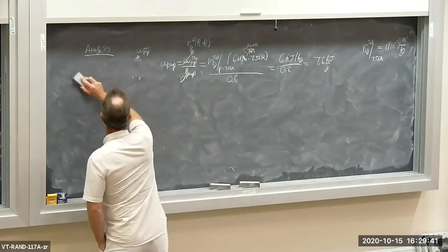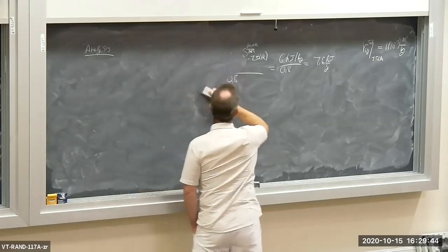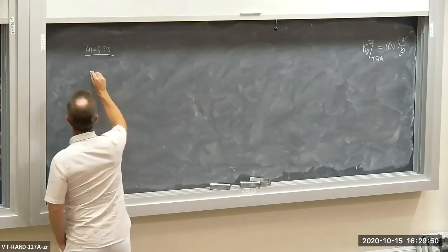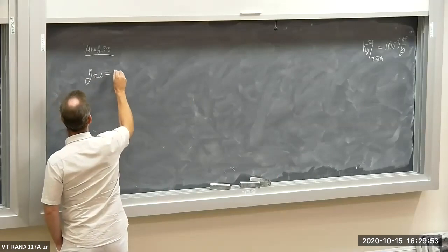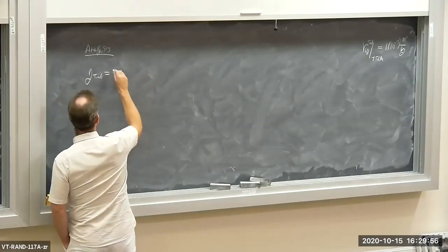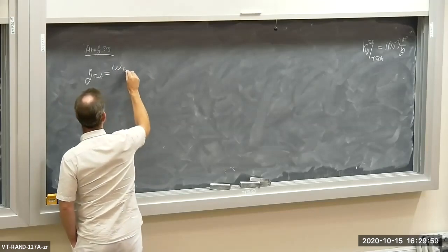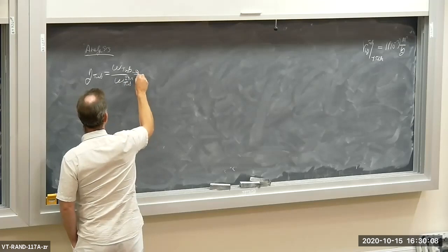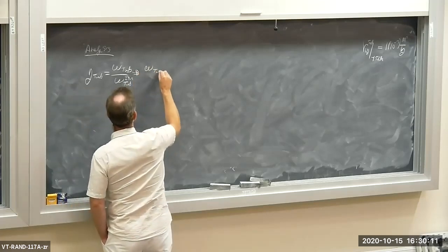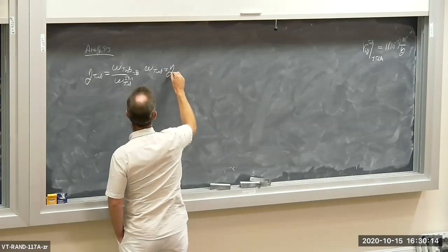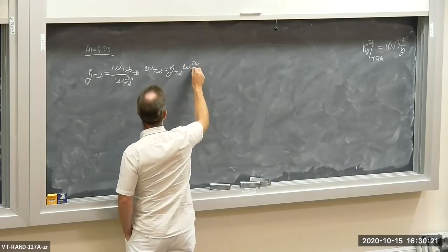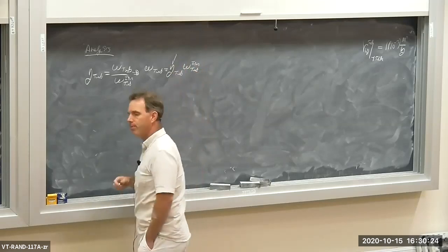So that's going to take a little bit more effort here. Let's use the isentropic efficiency for the turbine. The isentropic efficiency for the turbine is, mass flows are the same for the isentropic and the non-isentropic, so that's the specific work for the real turbine divided by the specific work for the isentropic turbine. So W turbine is equal to the isentropic efficiency for the turbine times the isentropic turbine work. Okay, I have the isentropic efficiency for the turbine.